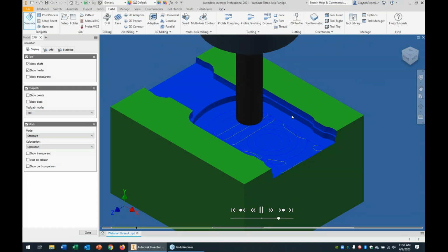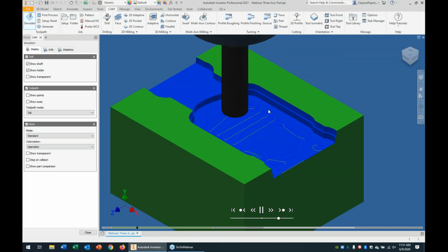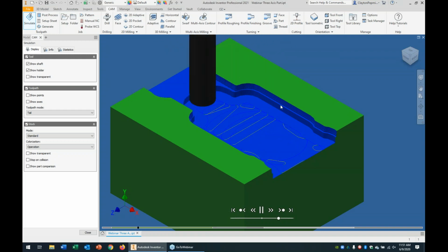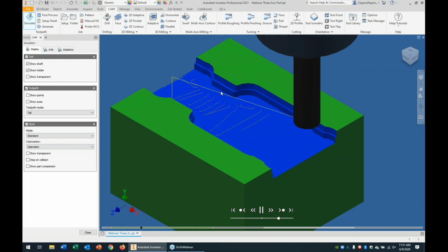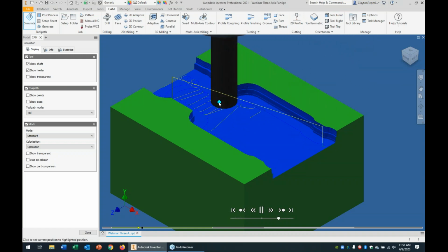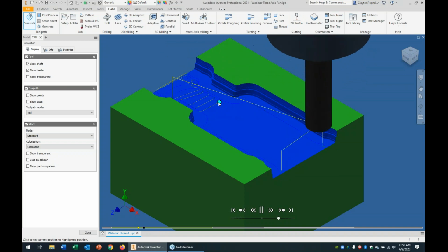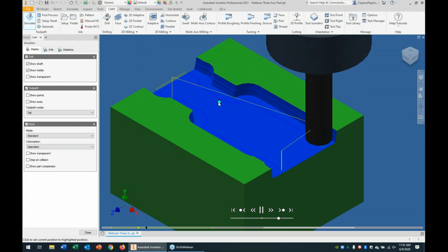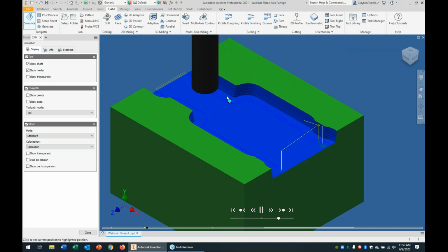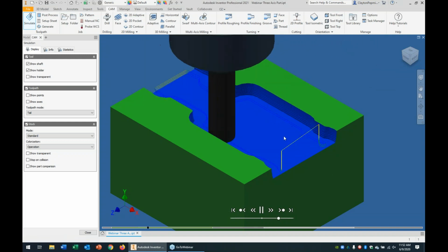But see that step over there on the wall? Because I went down, I forgot, 1/8 of an inch, I think is what I'm cutting with this tool. As you go down 1/8 of an inch, it kind of leaves a step there along that sidewall. You can see it more here on this curvature. What I'm doing with that minor step down is it comes back and takes pass 1. I told it to take 4 additional passes. There's pass 2. Sorry, 3 additional passes to make 4 steps. And there's pass 3. But see how I eliminated that step that was there?